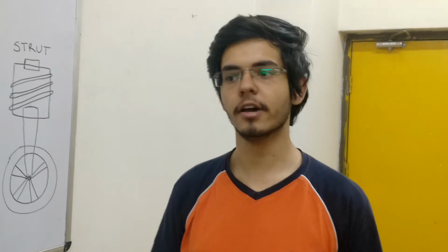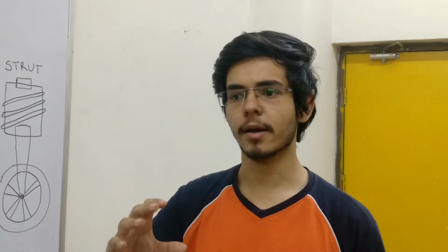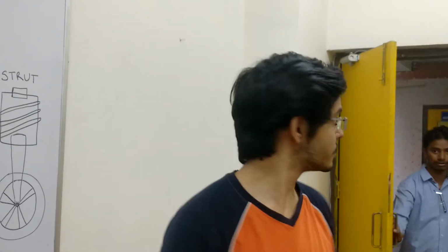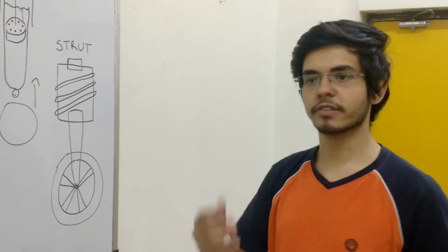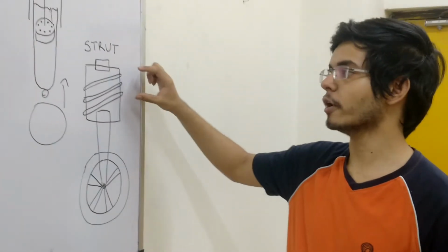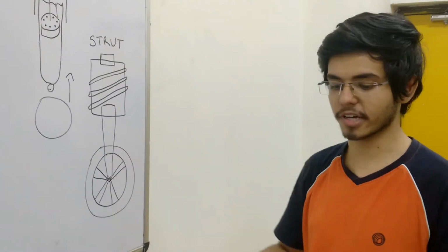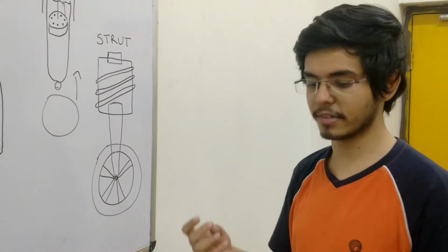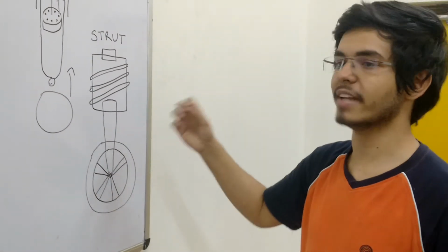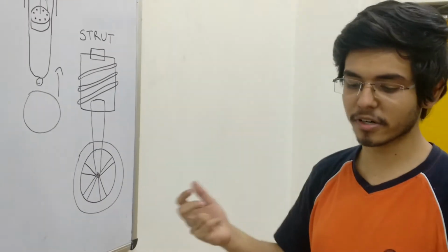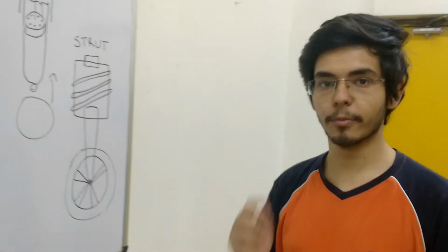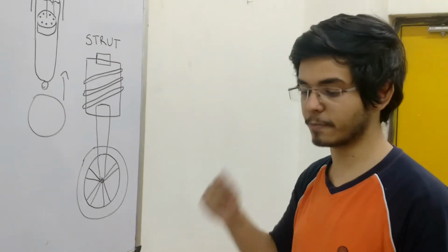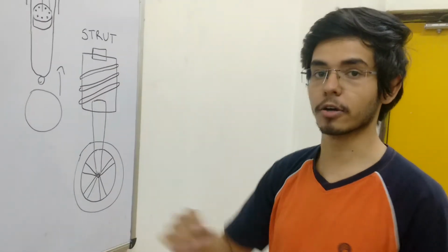So these days, the most commonly used type of suspension system is the strut, which not only combines the transmissibility of energy that a spring has, but also uses a damper in order to dissipate. So the strut is basically a combination of a coil spring and a damper, as we just discussed, and so it is a shock absorber mounted inside a coil spring. It's mostly known for its dampening function, and it provides structural support for the vehicle suspension. But the most important thing over here is that it controls the speed at which the weight is transferred in the car, but not the weight itself.